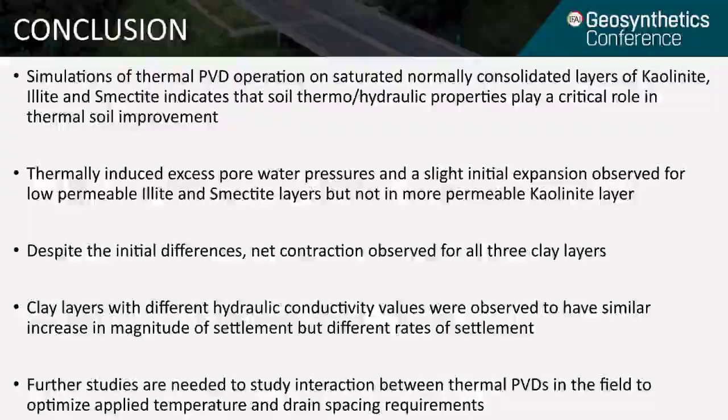Clay layers with different hydraulic conductivity values showed a similar increase in the magnitude of settlement, but different rates of settlement. Further investigations can be carried out on the interaction between multiple PVDs in the field to optimize the applied temperature and drain spacing requirement.